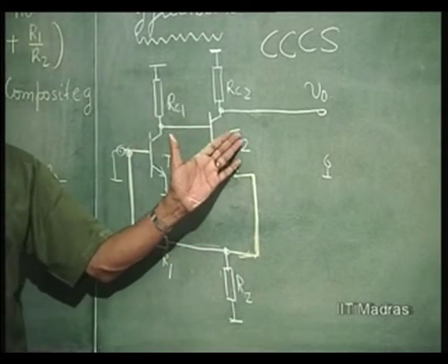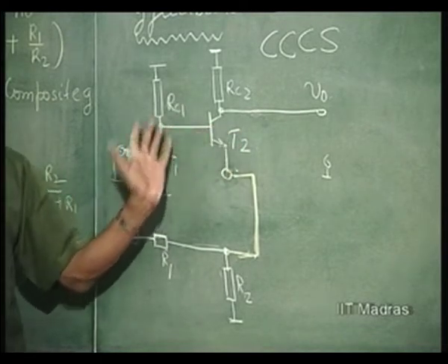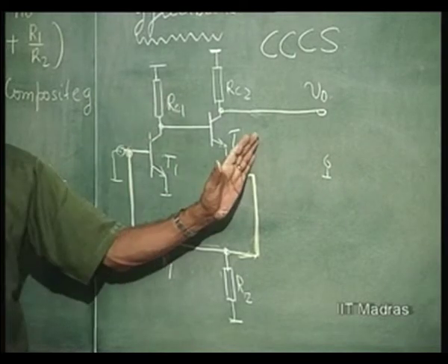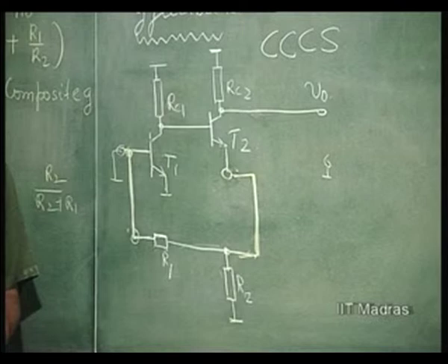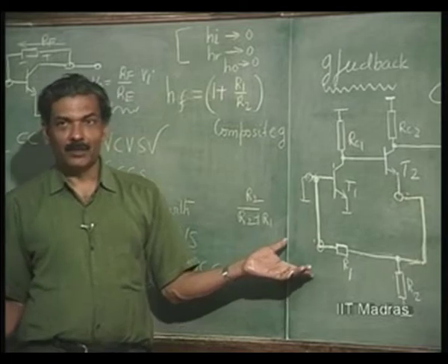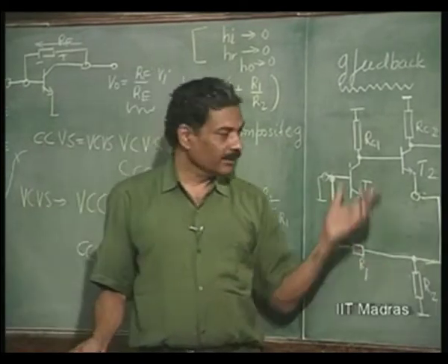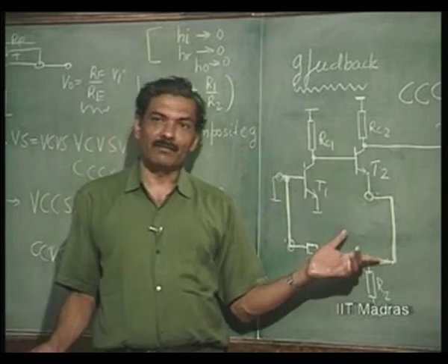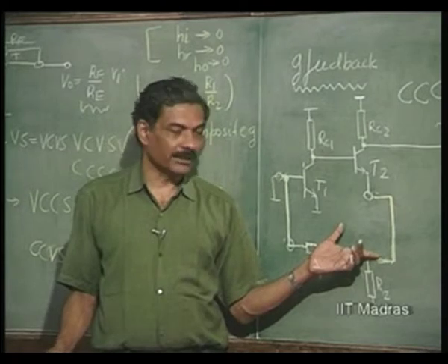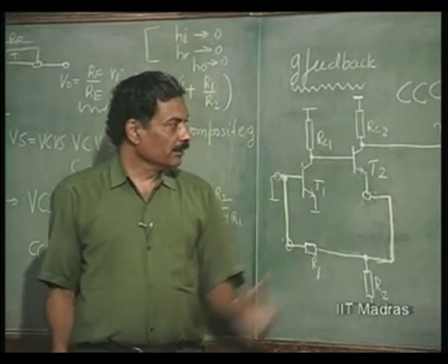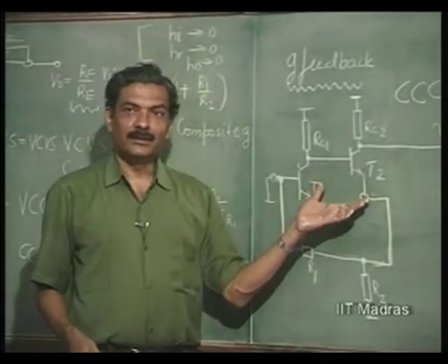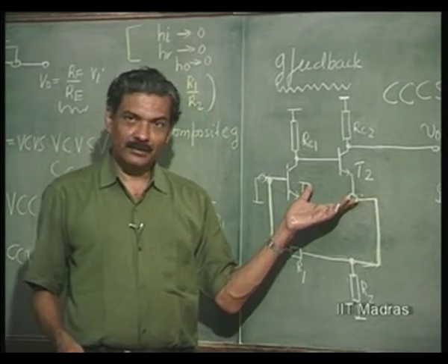As you cascade amplifiers, the individual time constants will cause a delay in the whole structure, and the phase shift will change in such a manner that what you consider negative feedback at a certain frequency will turn itself into positive feedback, and that is a danger. The positive feedback with loop gain greater than 1 will cause what is called instability in amplifiers, or oscillations. Okay. So, this kind of configuration for more than 2 pairs is definitely dangerous, right.